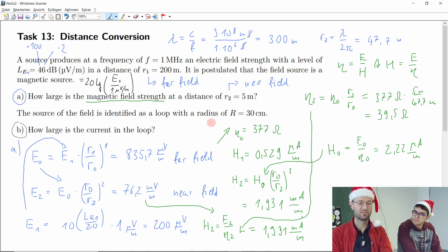We have calculated this current in the loop, for example, maybe in this power electronic circuit that generates this disturbance with maybe some kind of harmonic of a switching frequency. A power electronic circuit, but might be a resonant power electronic circuit, usually will not work at 1 megahertz, but maybe in the kilohertz range. But it could be, of course, some kind of switching harmonic that we have there that creates this current inside some loop somewhere on the printed circuit board.